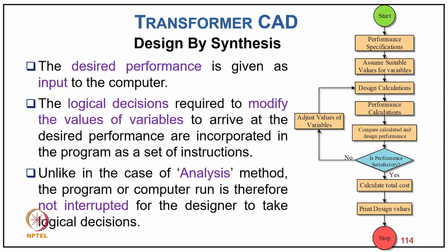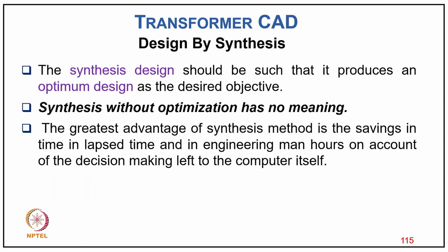So here, in step, the desired performance is given as an input to the computer, and the logical decisions required to modify the value of variables to arrive at the desired performance are incorporated in the program as a set of instructions. Unlike the case of the analysis method, the program or computer run is therefore not interrupted for the designer to take logical decisions. And the synthesis design should be such that it produces an optimal design as desired, and synthesis without optimization has not much meaning. So the greatest advantage of the synthesis method is the saving in time and engineering man hours on account of the decision making being left to the computer itself.